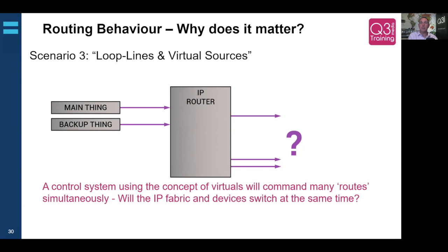A big problem here is if you're trying to switch the concept between main playout and backup playout, or main device and backup device, you expect all of your devices to switch simultaneously. And unfortunately, it's very unlikely, if not impossible, that they'll switch at exactly the same frame, which is what they would do in an SDI world.